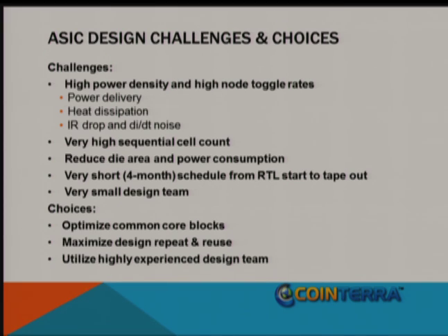Because of the high sequential count compared to combinational, we have to distribute the clock to all those sequential cells and also ensure a quality clock to all the cells. So that was also a challenge, and it took several iterations to close timing.